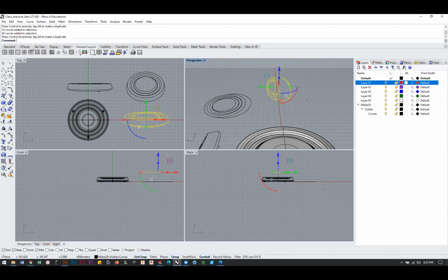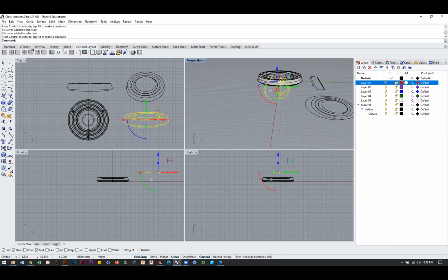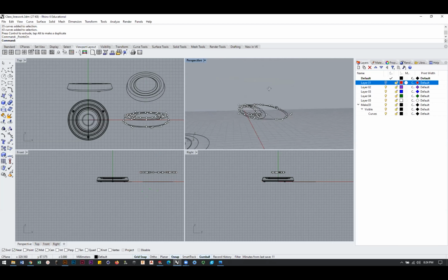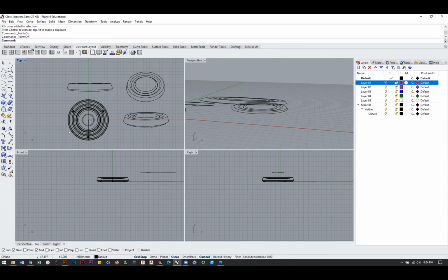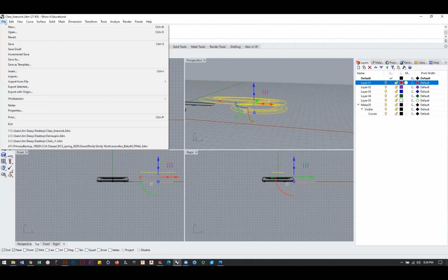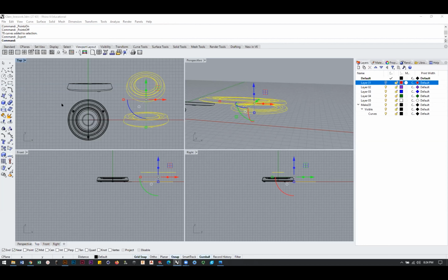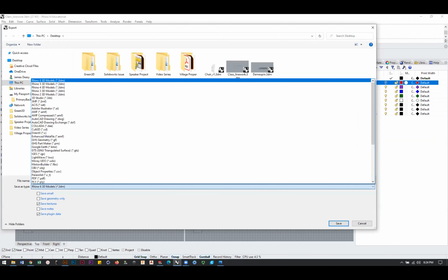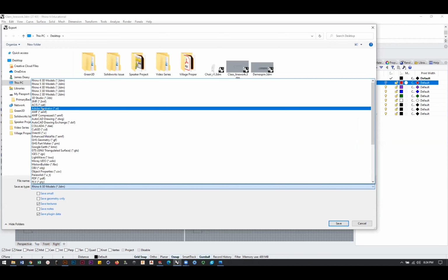These are just typical lines like any other type of lines in Rhino. You can turn on edit points if you want to see the crazy edit points that Rhino creates, just to prove the point that they're real line work. Yeah, so that's super helpful, and it's great news for presentation stuff, because what you can do with this line work here, you can select a set of line work just like this. You can go File, Export Selected. Okay, and then from here, you have access to a whole bunch of file types that you can save that line work as, one of them being Adobe Illustrator.